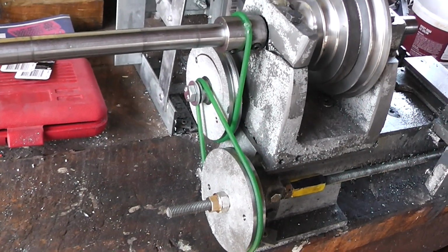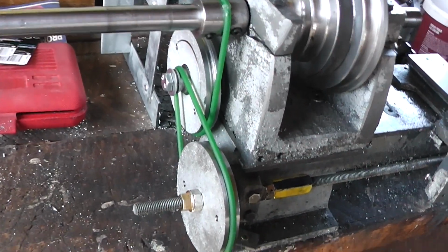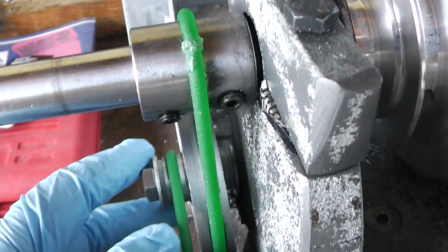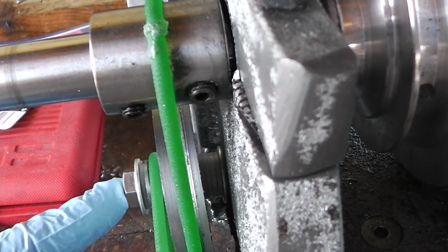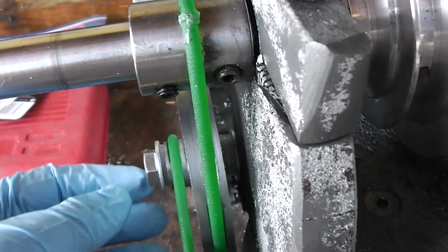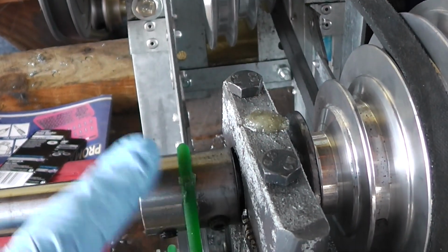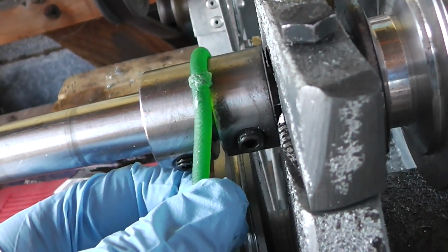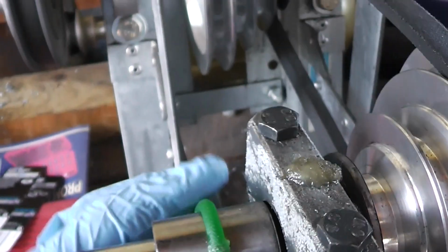Incredibly annoyingly, my camera died just before I started on these. So you saw me put this pulley on. I've also mounted this pulley as well, using some nylon washers as thrust washers. It's not a heavy load, so it doesn't have a problem. And for the pulley on this one, I've got two shaft collars next to each other with a small gap acting as the seat for these belts to sit on.